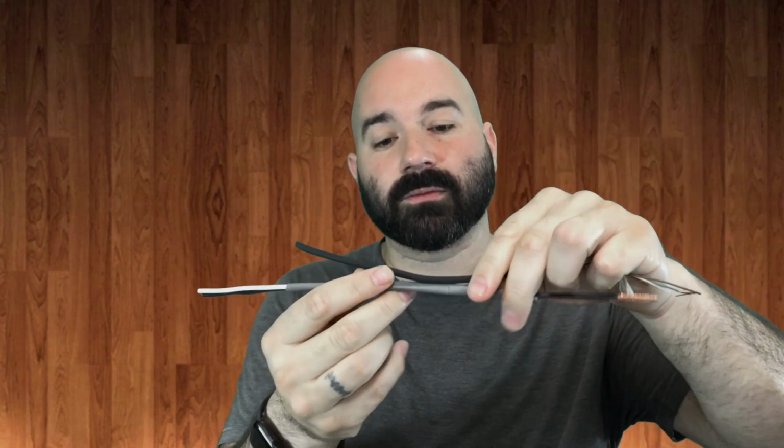The number one way to avoid EMI into your system is to avoid putting your audio cables together with power cables. So here we have a microphone cable, and let's call this a power cable. Just physically distance your cables away from each other. So I'll give you two scenarios. You have a power cable running down the side of a wall, and you have to run an audio cable down the same wall. So what do you do? Simply move them apart. Even moving them apart by 1 inch, having them run down the wall, can drastically reduce the amount of EMI introduced into your system.